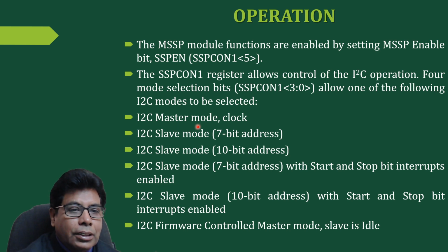So we have the master mode, then slave mode, we have 7-bit address, and another is 10-bit address. And then again in slave mode we have the 7-bit address with start and stop bit interrupts enabled, and 10-bit address with start and stop bits enabled. And one more mode is there, that is firmware controlled master. So here it will be only master mode.